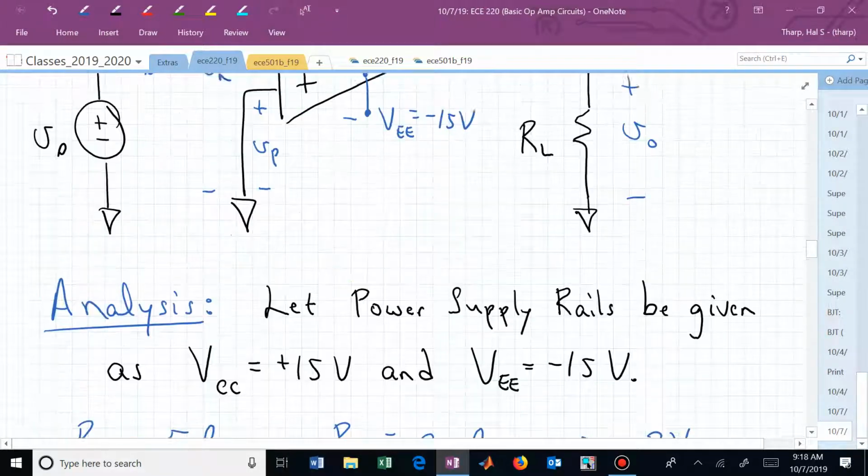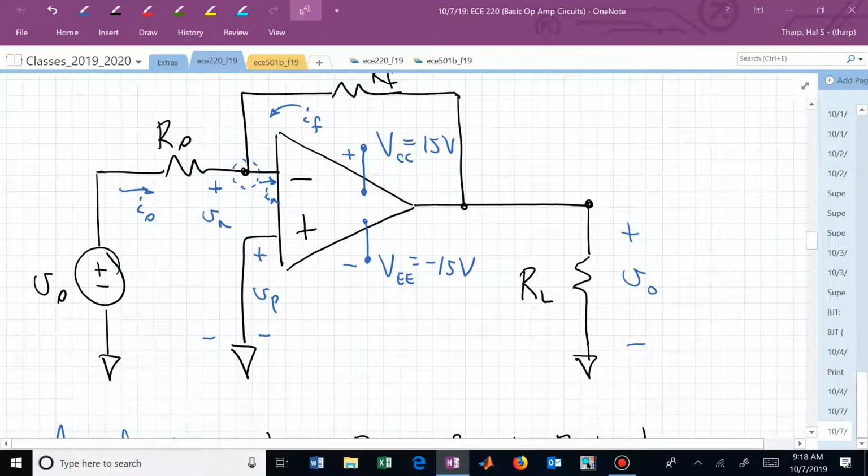And now let's go back into the circuit. Can you say anything about either of those by inspection of the circuit? What is V sub p? Where are we connecting the non-inverting pin of our op amp? To the common node, which we're saying is 0. That's our 0 volts, which we're connecting with a wire to the non-inverting pin. That's at the reference voltage, or the common voltage. V sub p is 0.